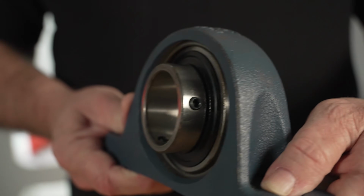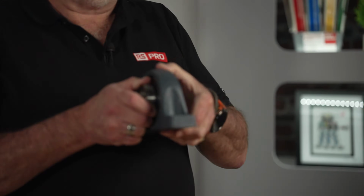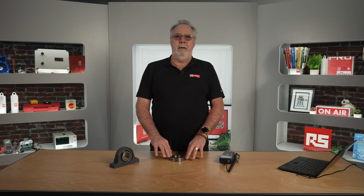If the shaft is bent, then the bearing will wobble, and that will cause the outer ring to move in the housing, which is not designed to do. The evidence of that is cast iron below the housing. Once you see cast iron or you see a shaft that is wobbling, you need to change the whole unit, housing and bearing.